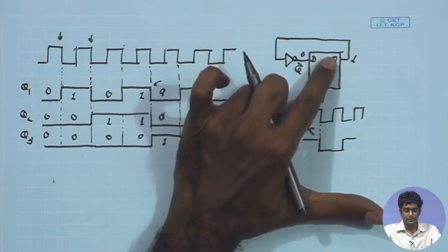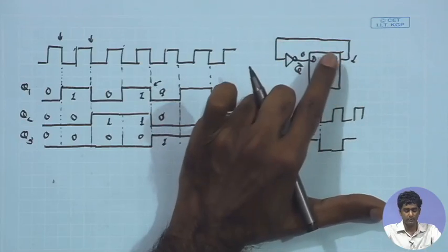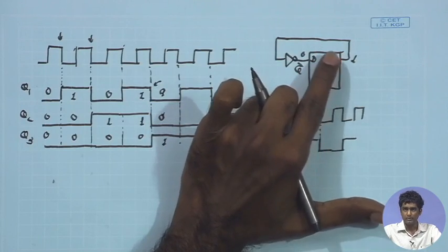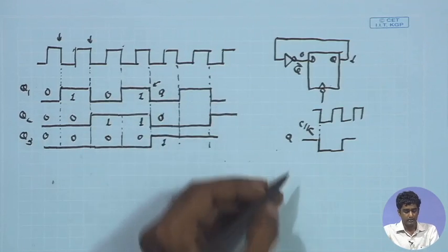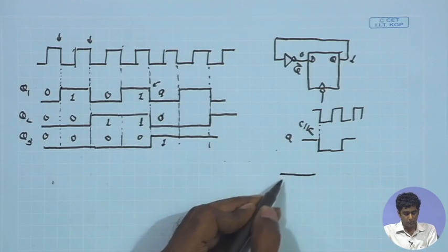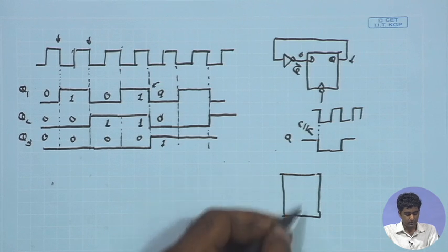The flip flops do have the complementary outputs coming in. So, in most circuit implementations of the flip flop, you will have the Q and Q bar, the logical inversion of Q, also available from the flip flop circuit. So, I can use the Q bar to implement the toggling operation.